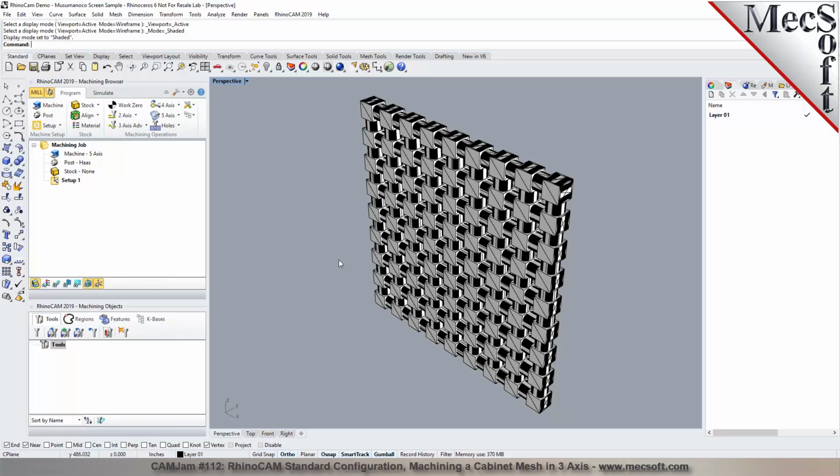The first thing we're going to do is, you initially do a mental checklist when you first open the part. Is it in the right orientation? What are the units? We're in inches. Is that correct? It's an inch part? Yes. Okay. And we know from the geometry that it's a mesh. And for the orientation, we see that it's not in the correct orientation. RhinoCAM has a real easy tool to orient your part for machining.